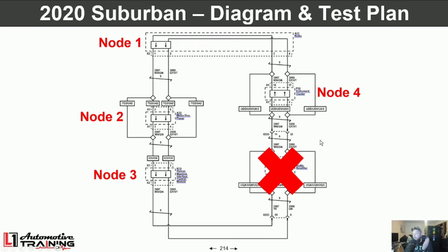We know we're not dealing with an amplifier problem. It doesn't even have that. I want you to also notice that I didn't call out in this particularly, but X225 is the only two that go around this. That means it would go out to an amplifier and come back, and there's a lot of that on these vehicles. So there's not many connectors anywhere else on this system, as you can see, and it is a twisted pair of wires that is the TXRX.